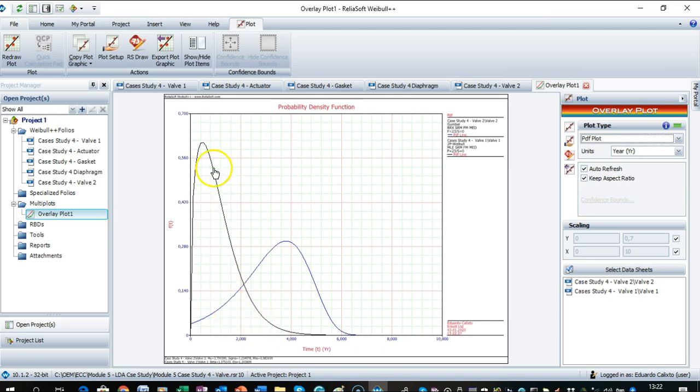So the first one, because I just get the interval between the dates of the failure without looking at the components, the cause, I predict a log normal. But by getting the proper definition, I get a Gumbel. So here in one case, the failures are concentrated in the very beginning of the life cycle.